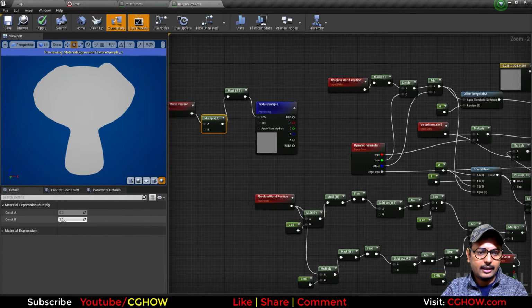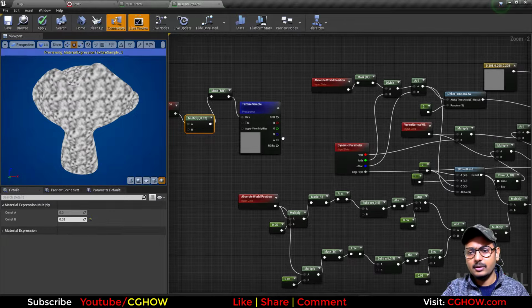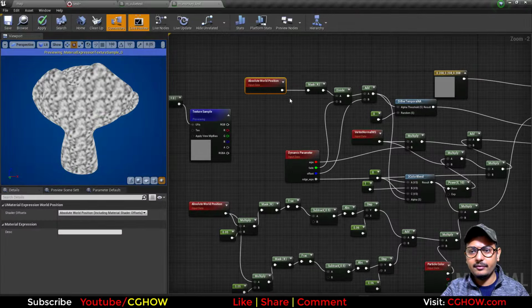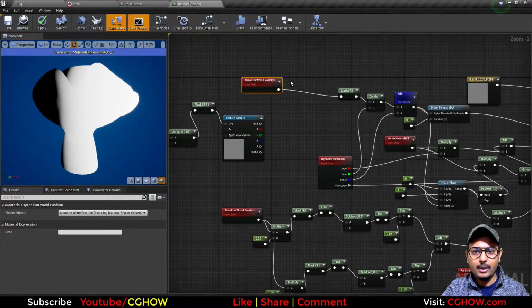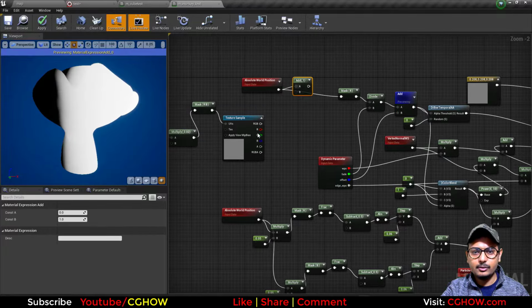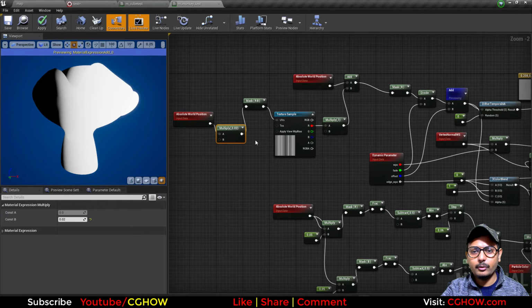You need to make the tiling little lower, 0.05, 0.02, maybe this much, and then this is where you're getting that edge, so you need to add this noise texture here, but before adding I will multiply to control how much distortion I want. So we have now two parameters. This is for noise styling, this is for distortion control.